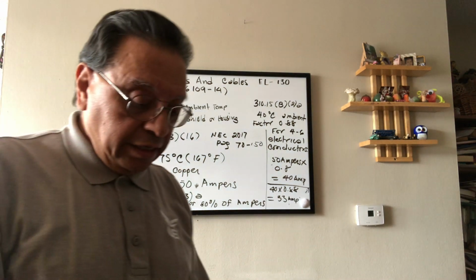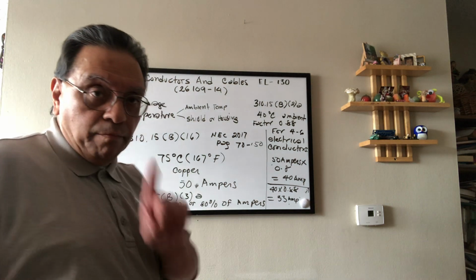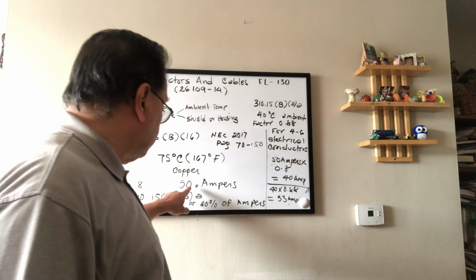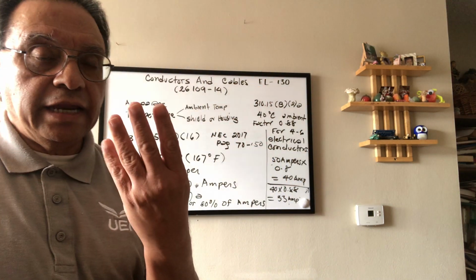So in reality, this electrical conductor number 8 by itself is able to transport 50 amperes. But that is when combining a maximum of 3 electrical conductors. But now we need to add a fourth electrical conductor. We have 3 phases plus the neutral. The ground doesn't count. Then there are 4 conductors transporting electrical current.